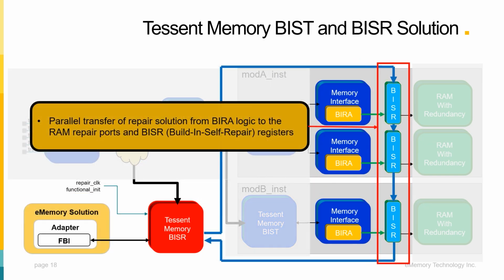Subsequently, repair information is transferred in parallel from the built-in redundancy analysis logic to the RAM repair ports and built-in self-repair registers.